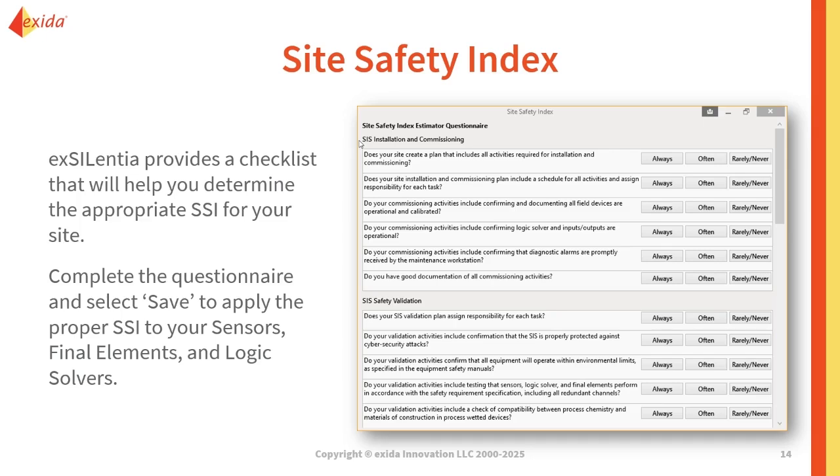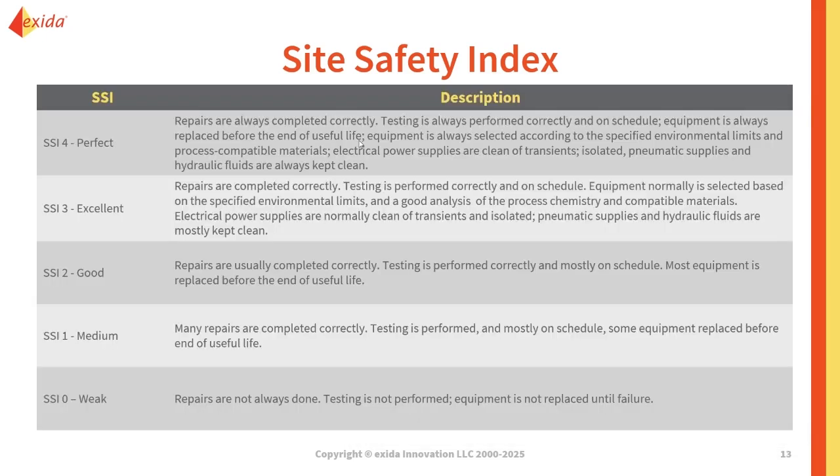If you prefer not to consider this within exSILentia, you can assume that it's perfect, but it's good to read exactly what we would expect from SSI 4, which we call perfect repair. As I mentioned, you'll see it default to SSI 2, assuming that you're keeping up with this and, at times, things aren't always done completely to schedule.